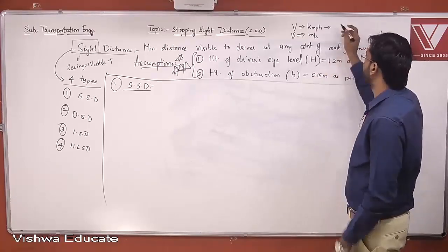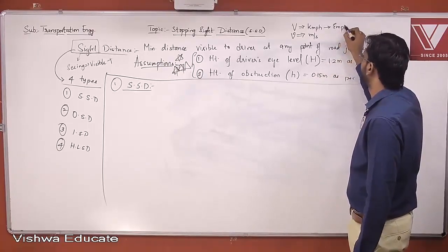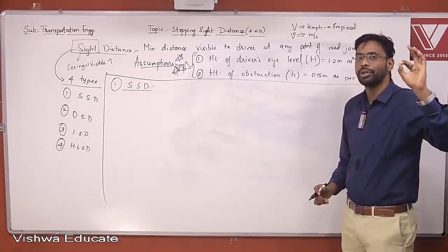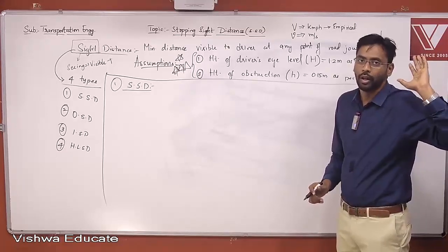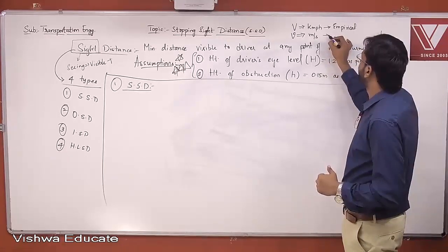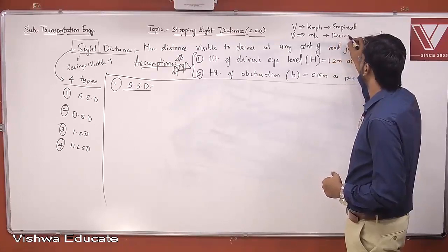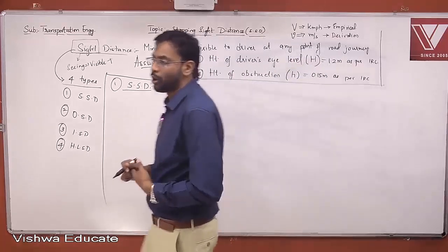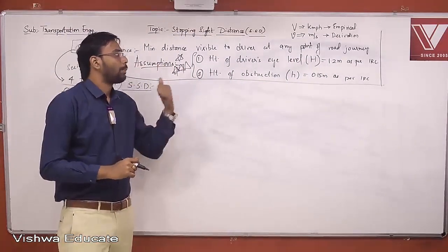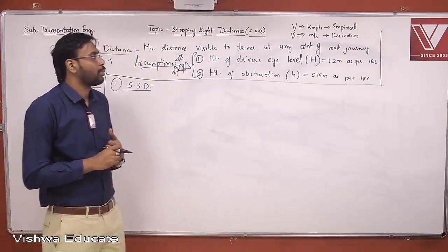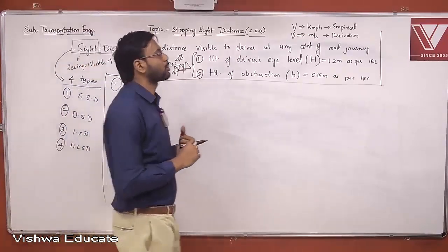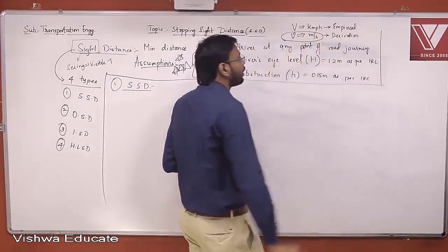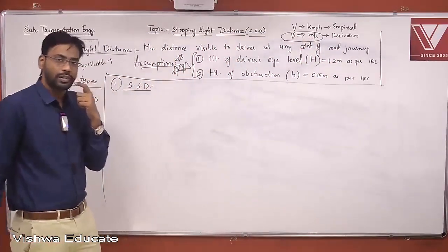That's called an empirical equation, an empirical formula. So there will not be any logic, and you should use the same units which were given in that formula. If I'm going to do any derivation or any logic, then I'll be using small v. Capital V is design speed in kmph and small v is in meters per second. In most of transportation engineering, I'll be using small v only. If I use capital V, then I'll be stressing you at that particular point.